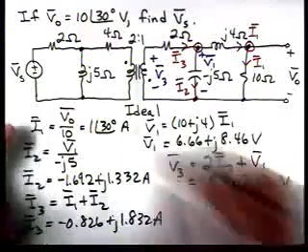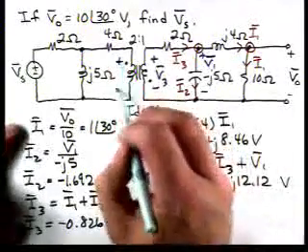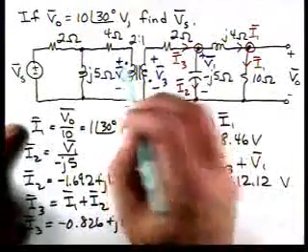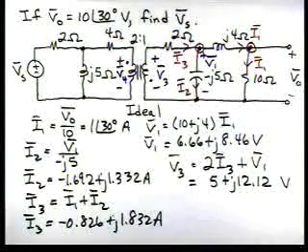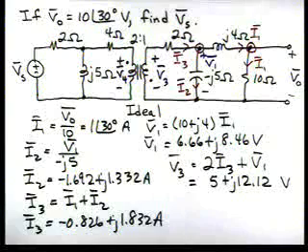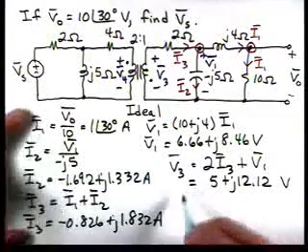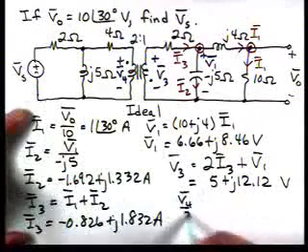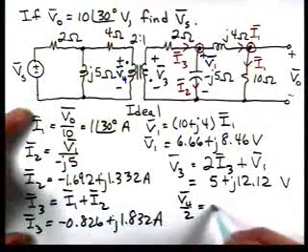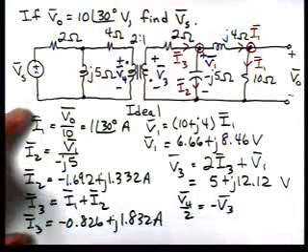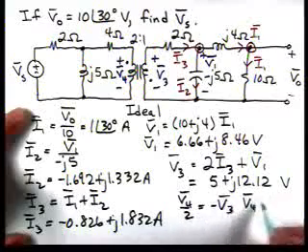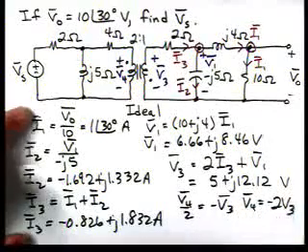And if we say, well, let's let this voltage be V4. And if we note that V4 is polarized at a dotted terminal and V3 is polarized at an undotted terminal, then we have V4 over 2 is equal to minus V3, or V4 is equal to minus 2V3.